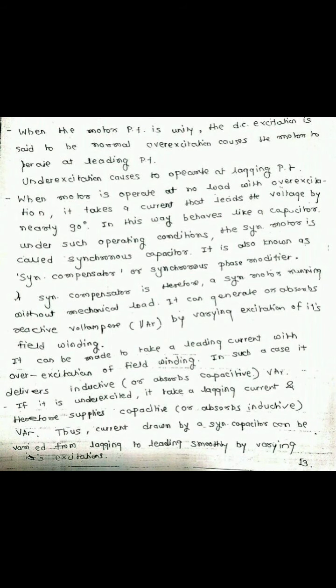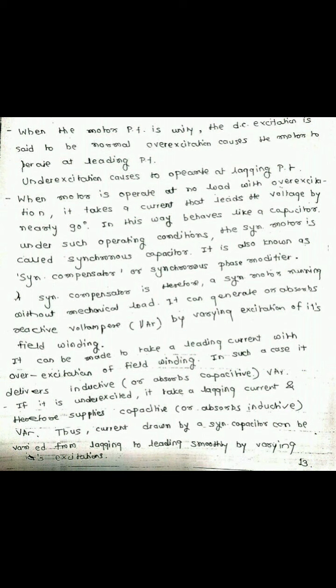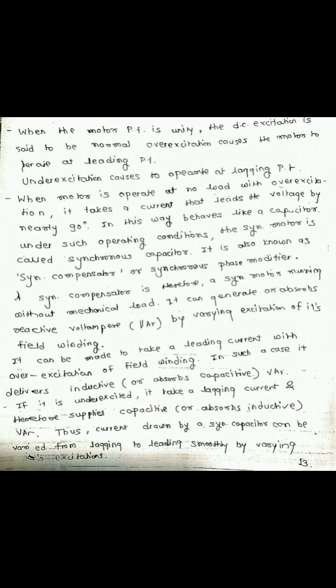The important concept is that when the motor operates at no load with overexcitation, it takes a current that leads the voltage by nearly 90 degrees. In this way, it behaves like a capacitor and is called a synchronous capacitor. It is also called a synchronous compensator or a synchronous phase modifier.